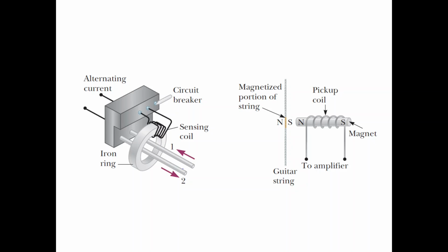Imagine that everything is fine, and there is no situation with potential on the metal housing, and everything operates under normal conditions. According to continuity and conservation of electric charge, we have equal currents which flow in and out. That means they compensate each other in terms of the magnetic field which is created.